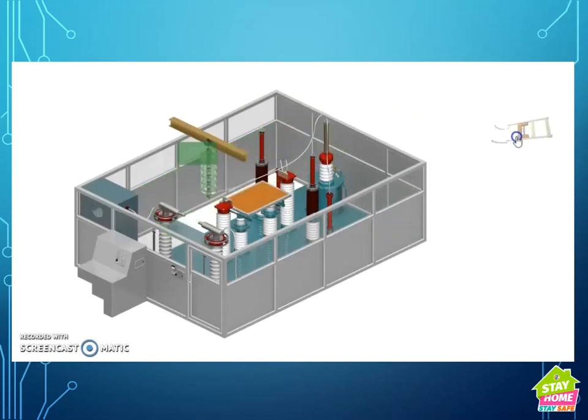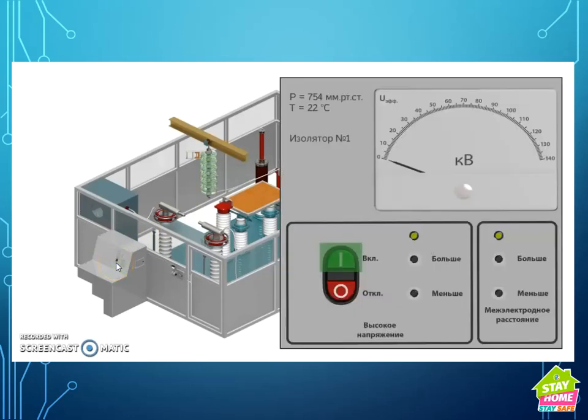We determine the voltage at each insulator using a discharging stick. Then we need a shorting wire. Put it on the 4th insulator to make it defective. And then we make a circuit on the insulator under study and apply voltage to the garland until a breakdown occurs on the stick between the metallic balls. Let's see.